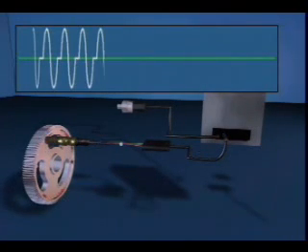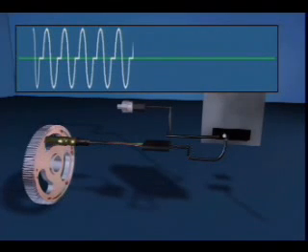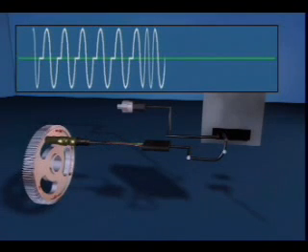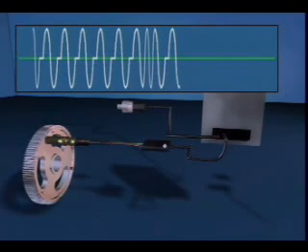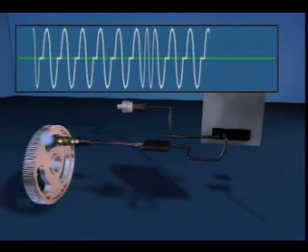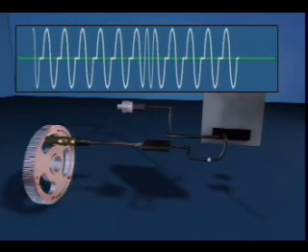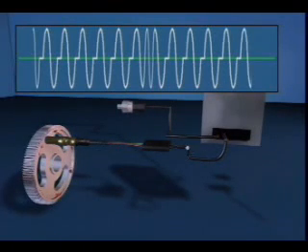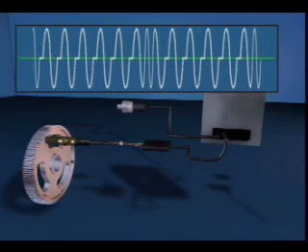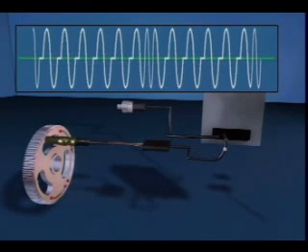The 7th protrusion on the cam gear is located 30 crankshaft angle degrees after cylinder number 4, the last cylinder in the firing order, or 90 crank angle degrees before the protrusion for cylinder number 1. Because of its location on the gear, the signal from the 7th protrusion breaks the consistent time interval of the signal from the other 6 protrusions. The ECM interprets this 7th signal input as the beginning of a new cycle in the firing order and generates a timing reference signal for the ICM.